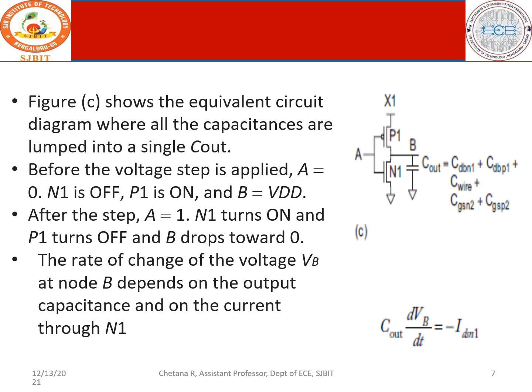So CD N1, CD P1, C wire, and the source capacitance of N2, the source capacitance of P2. All these are added and we call it Cout, inclusive of the wire capacitance. So this is the simplified diagram of the inverter which was being considered in the previous example, or in other words we can call it an equivalent circuit.